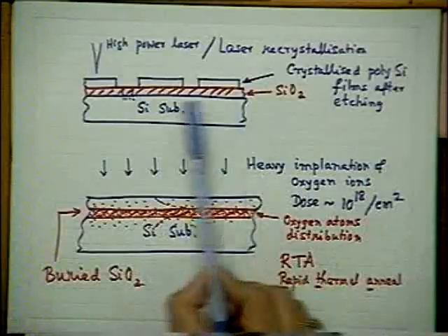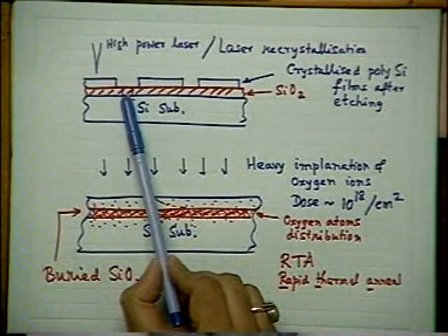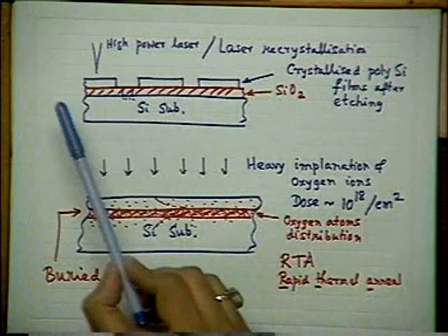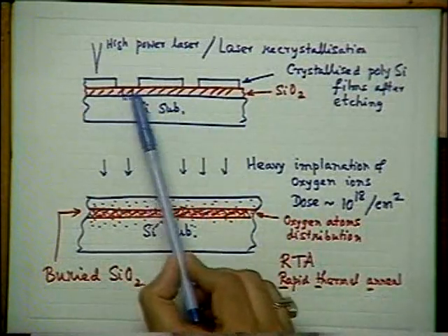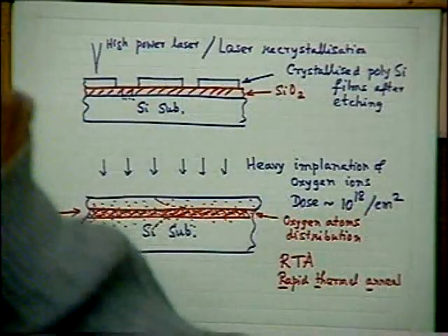After etching, the oxide does not fully cover the surface. Rather, in certain locations, there are strips where bare silicon is already available. Then you grow polysilicon, then sweep the laser beam, and ultimately you get better quality films. As I told you, research is still going on, but commercial products are available using both these techniques for very high-speed space applications.